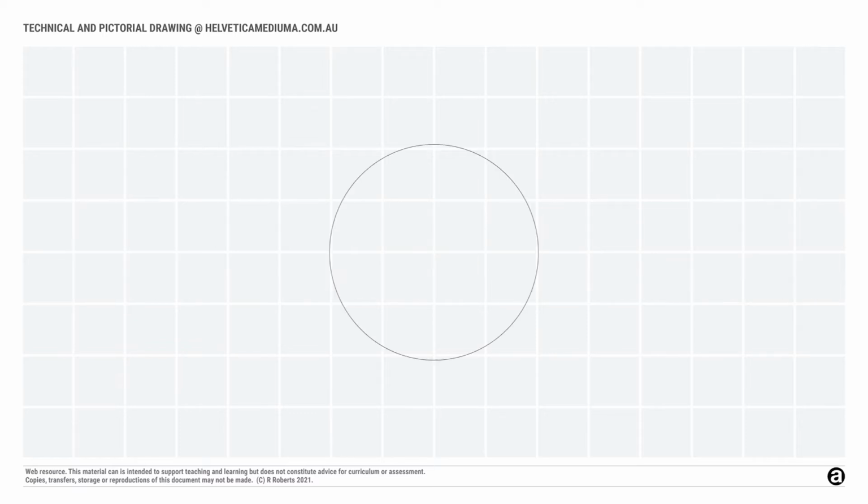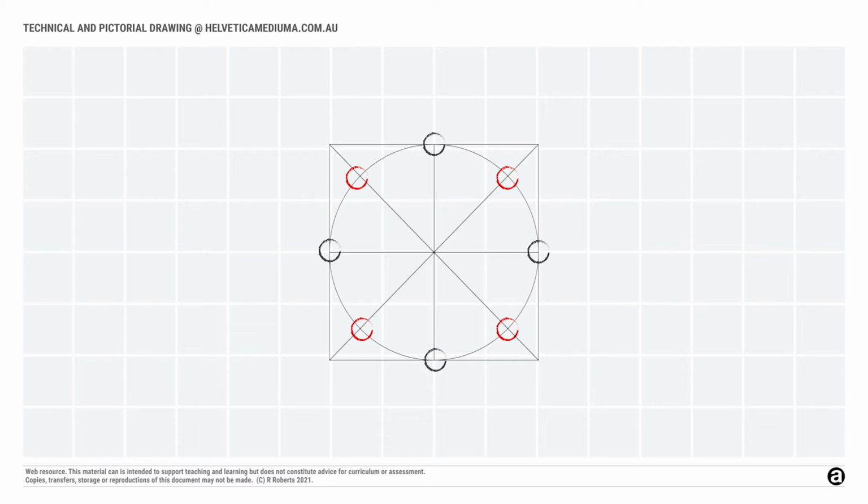I'd like to start by thinking about a circle and its relationship to a square. Now we all know that the circle touches a square at midpoints. Then we're going to have to identify where the ellipse also happens between those points. So I draw vertical, horizontal and diagonal lines. Then I draw a diamond between the center points on the square.